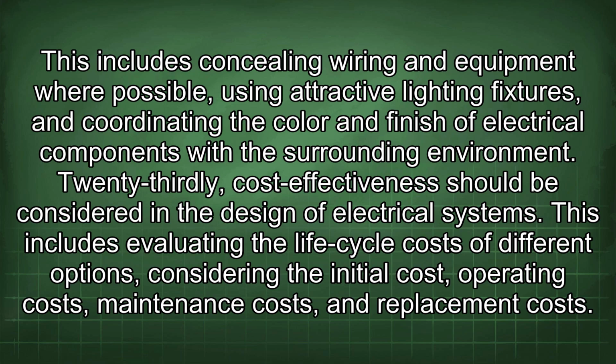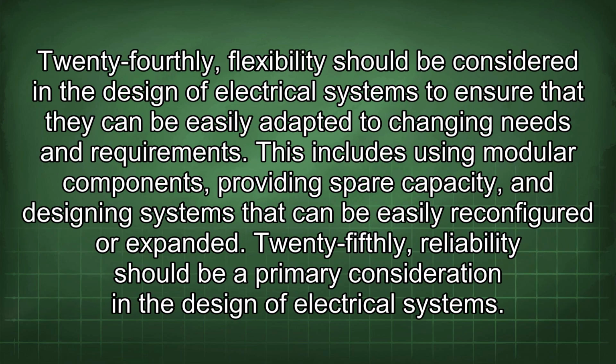23rdly, cost-effectiveness should be considered in the design of electrical systems. This includes evaluating the life cycle costs of different options, considering the initial cost, operating costs, maintenance costs, and replacement costs. 24thly, flexibility should be considered in the design of electrical systems to ensure that they can be easily adapted to changing needs and requirements. This includes using modular components, providing spare capacity, and designing systems that can be easily reconfigured or expanded.